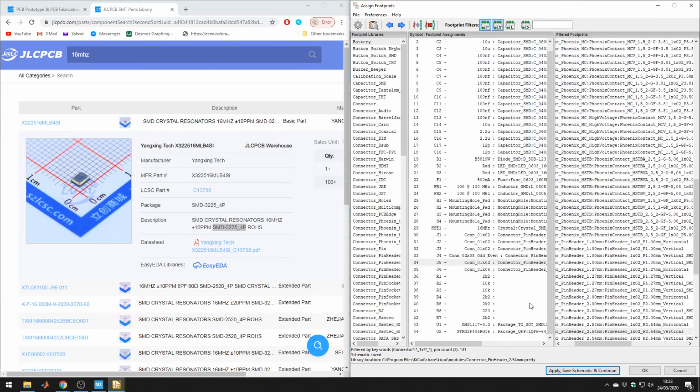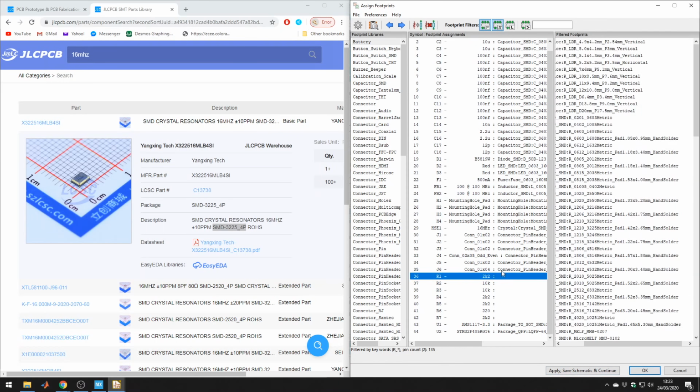Awesome. Okay, now finally we're coming to the resistors. Now resistors, again, it depends. If you want to change them later, go for a larger size. If you think you're going to fix them, go for the smallest size which is possible, plus watch out for the power rating. So for the LEDs, calculate what current will be going through them, the value of the resistance, and you work out what power will be dissipated in that resistor.